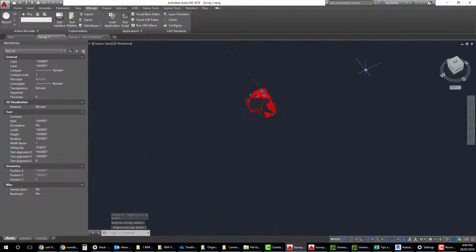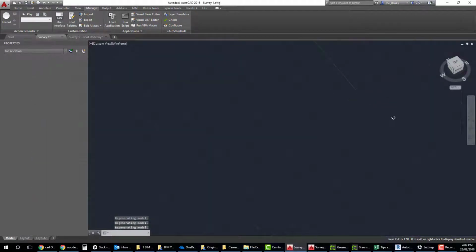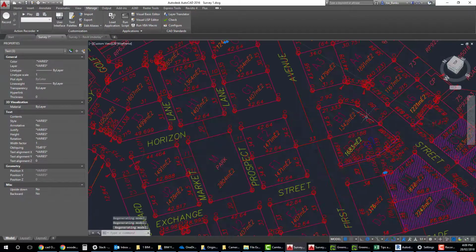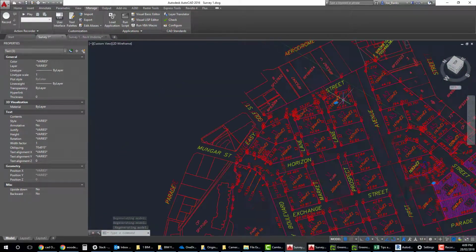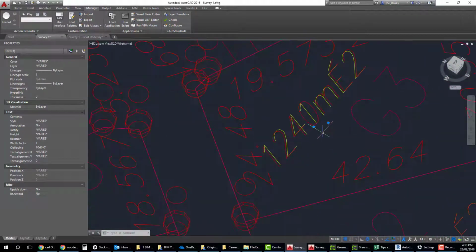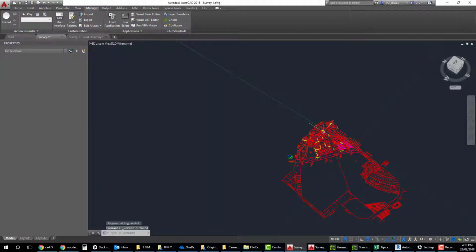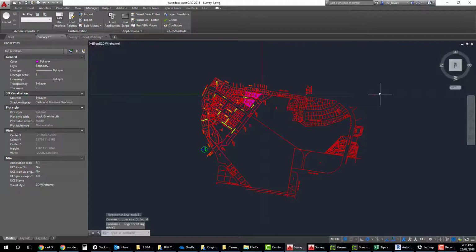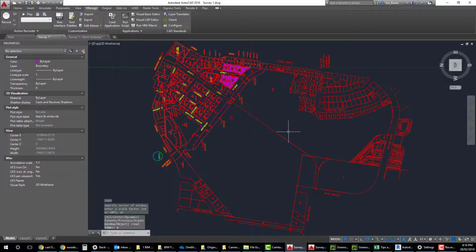Okay, yep. So that text has its origin way over here, and that's potentially what's causing that zoom to look funny. So you can have a look at those 2 pieces of text and see if they are valuable. I'm just going to delete it for the purposes of this. We go back to the top now, do a zoom all. Now you see that the zoom all fits nicely within here.